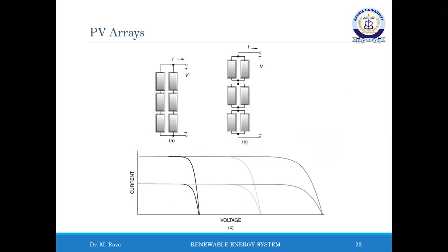When high power is needed, the array will usually consist of a combination of series and parallel modules, for which the total current voltage curve is the sum of the individual modules' IV curves. There are two ways of imagining wiring a series parallel combination of modules. The series modules may be wired as a string and the strings wired in parallel, or the parallel modules may be wired together first and those units combined in series. You can see the difference between the two strategies in these two diagrams.